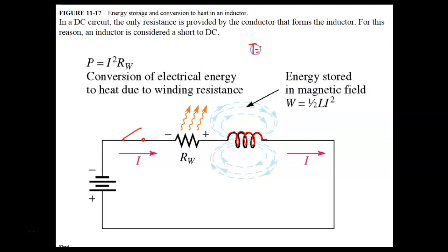One time constant is equal to L over R, and this is that 63% thing. Time to fully charge is L over R times 5. It should be on your formula sheet. Inductors are on the back of your formula sheet. These are your basic formulas.